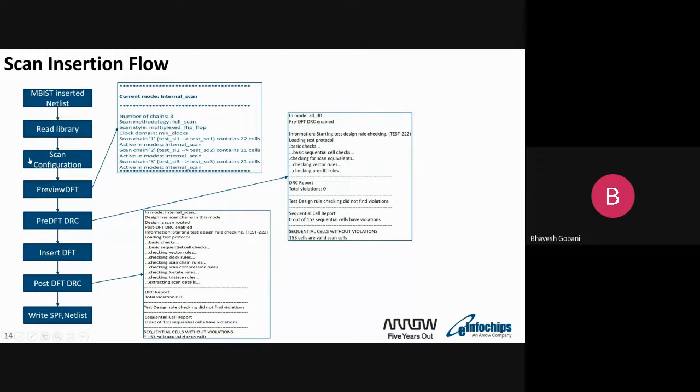Once scan configuration is done, I will run preview DFT. It will try to identify the pre-checks, we can say. It will give reports on how many chains could be created, how many inputs, whatever configuration we set. Based on that, we see whether we are getting the expected result or not in different modes, test mode.